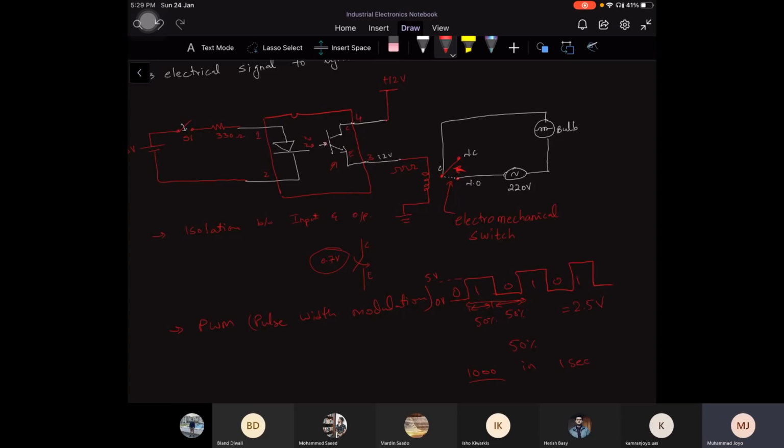And second thing, what will happen is that when you increase the frequency or the speed of the motor, the bar will get stuck to one of the terminals, maybe to normally open or maybe to normally closed. It will be completely off or completely on.